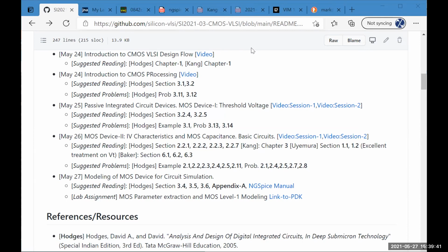If it is not in the model file, you pass it. If it is not in the model file and you're not passing it, but you know it, then you calculate it like what Santanu was saying. You include it in the source drain areas. You got it. But typically you always have those parameters. Model parameters are in the model, right? Because they are not design parameters. Design parameters are source areas, drain areas, W, L. Everything else is process parameters. If it is a process parameter, it goes into the model, right? So that's how it is.